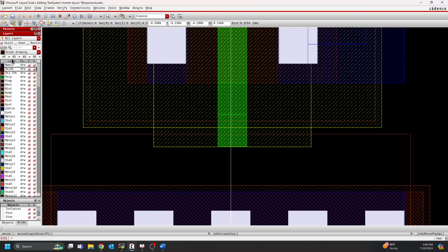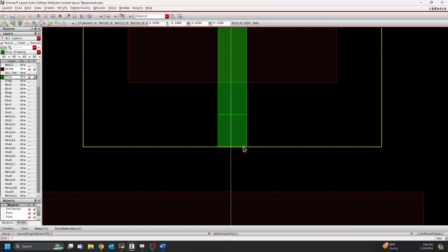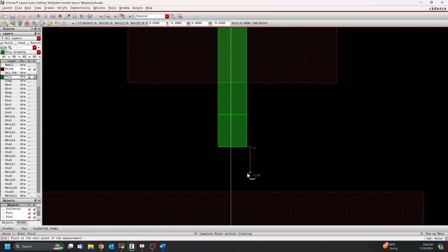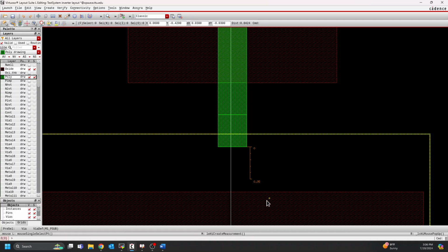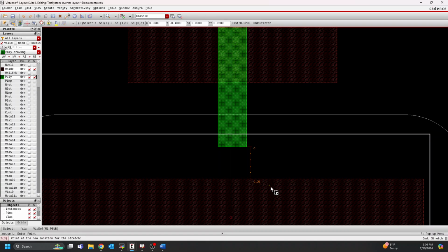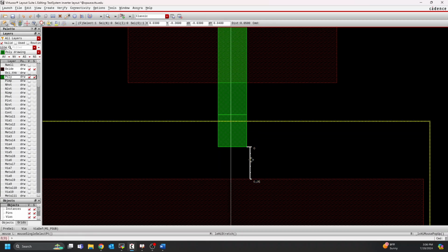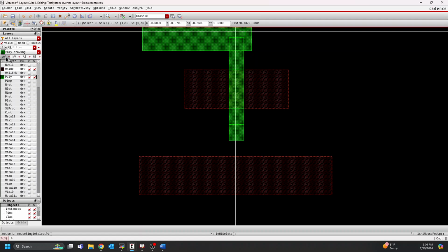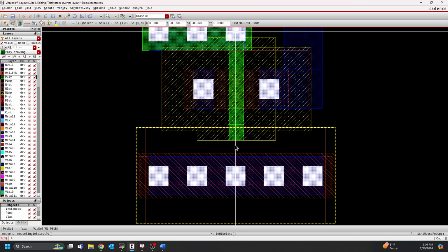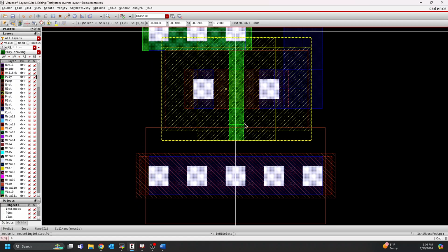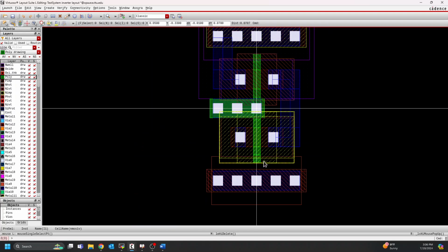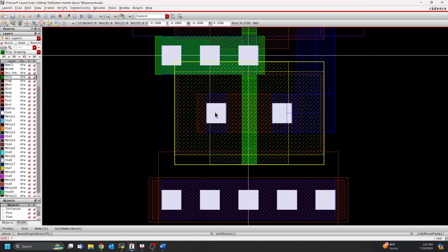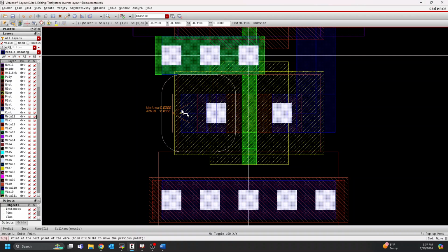So we know that the oxide and poly layers have to be spaced apart by a certain amount. So if I press K here, we can say 1, 2, 3, 4, 5. We can go ahead and scoot this guy up a hair to make sure that they are optimally spaced. It's not really optimally spaced. There's not an optimal location for this to be, but it does help it be more spatially efficient. So we're making it as small as we possibly can. We can see that everything's kind of centered as well as we can get it, so that's kind of looking good for us. Now we can just make another path here. So we can make a path on this guy, make sure we select metal 1, and then we're just going to have this connect to this body contact here.